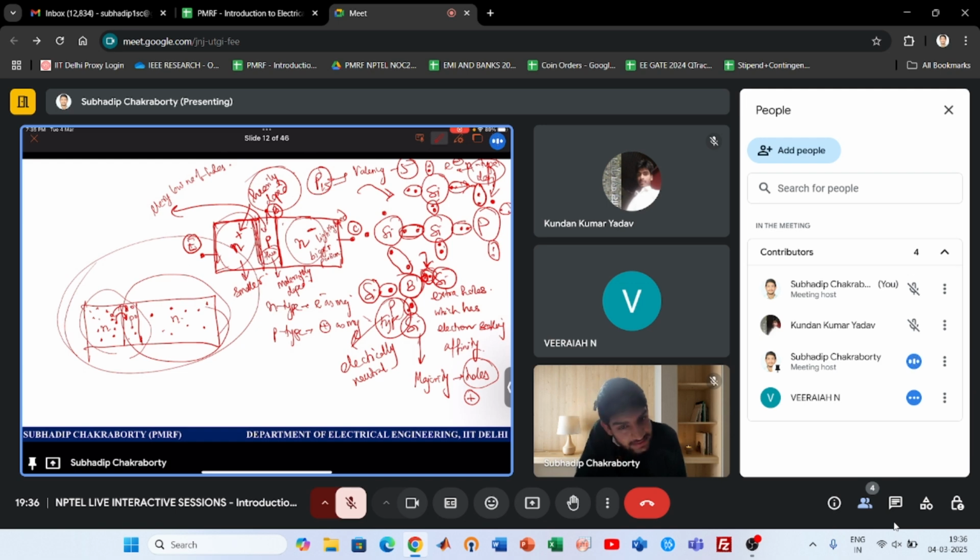Then what will happen? You have some portion internally with negative and positive, right? If an electron jumps from this side to this side, we can imagine that holes jump from this side to this side, just like that. And that's why a reverse electric field region will be created, which opposes further flow of electrons from this side to this side. So the process itself will retard with time. Otherwise, all the N-type material will go to the P-type and everything will be gone. Such things don't happen because nature itself opposes by creation of an internal electric field.